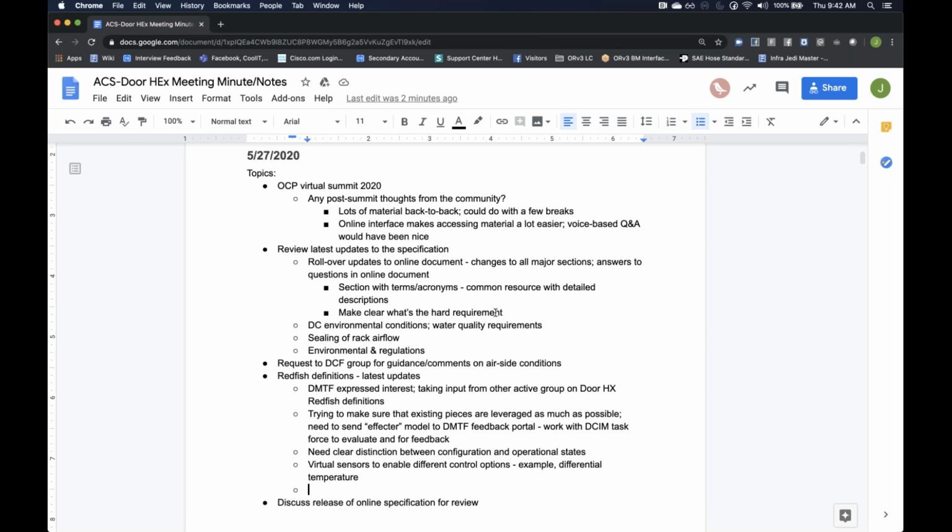But yeah, we were actually looking at doing it a little bit lower level than that, so that the controller might have multiple digital I/O pins on it, and if you chose to, at installation time, you could wire a micro switch and mount it on the door. Right. And then you would go into the configuration mode, say potentially for the fan speed effector, and say that there's an interlock on this particular effector, and if this interlock goes to the true condition, then turn the fans off. Yep, and we can do that too.